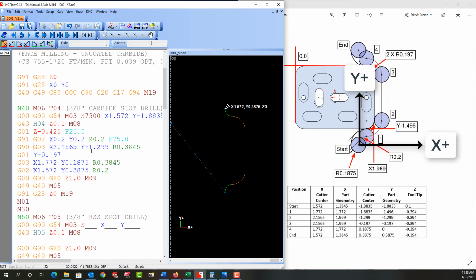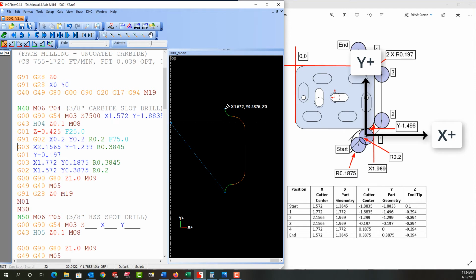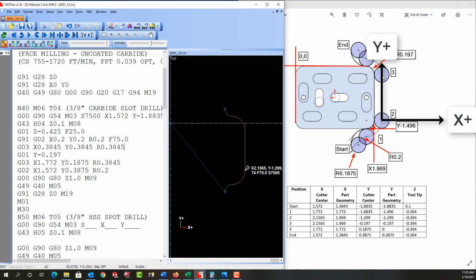So we'll continue to convert these to incremental. I'll delete the G90. This is still a G03. Again, the radius won't change. So to go from here to here, we're sweeping through a full 90-degree arc. Here's now my Cartesian coordinate. Once again, we're going to go in the x plus and the y plus, and they'll equal the radius. So next, I want to program still G01, but incrementally from here to here. There's no change in the x, but there is a change in the y. I go from the y at position 2 to the y at position 3. So the incremental is the difference between these, and it's in the y positive with my Cartesian coordinate here.